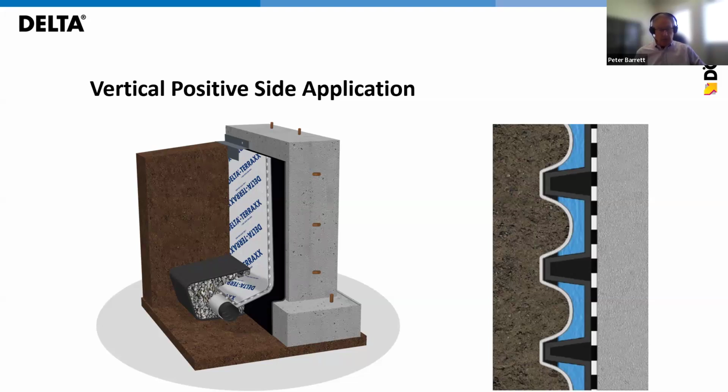Having a high flow rate capacity ensures effective drainage and helps prevent the buildup of hydrostatic pressure. Also important, we do not want the geotextile to rot, and at the same time, we do not want it to allow dirt particles through to clog.